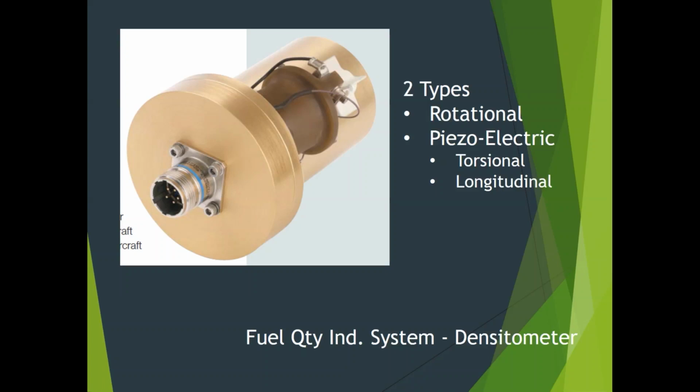You put some fluid on there, a less dense fuel, maybe that slows it down to 29,000 hertz. That feedback ends up being 29,000 hertz. You put a more dense fluid in there, colder fuel, a different grade of fuel that's more dense. Now maybe it slows it down to 28,000 hertz, that feedback signal, okay?